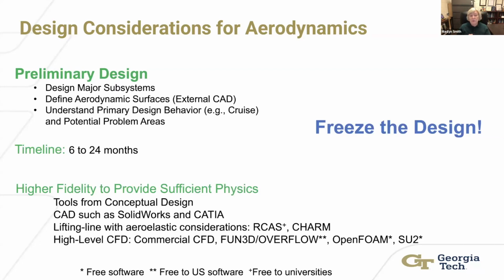And let me say here too, while you're doing your preliminary design, I'm focusing on aerodynamics, but it's inherently aeromechanics. So when you're doing your aeroelastic considerations with these codes, please make sure to take a look at your vibratory loads. I think the RCAS and CHARM level tools are what you need, but you need to make sure that you're not going to have vibratory loads that contravene your requirements.